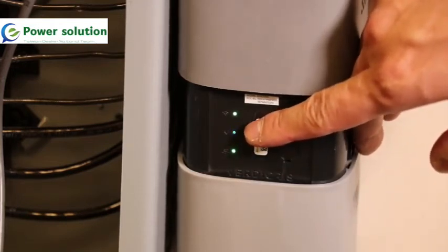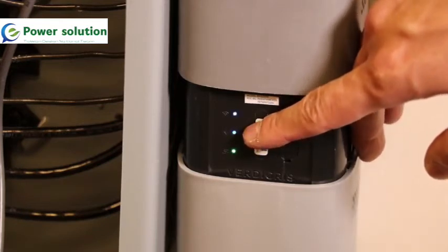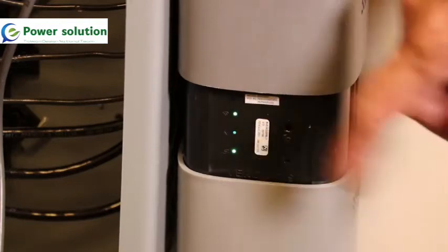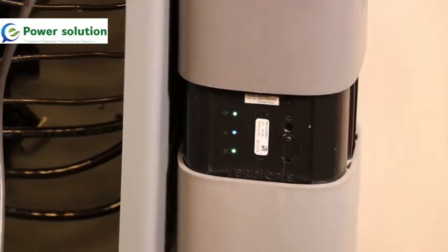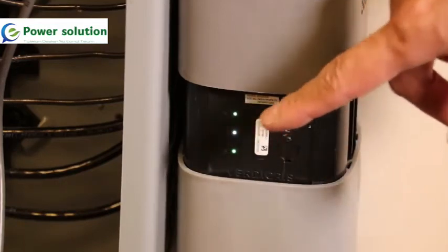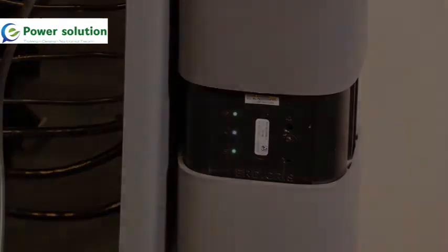The next light we expect to turn on is the voltage light, and the voltage light will go solid based on the color of the indicated voltage. We won't worry about the top light yet because that's related to the commissioning, and that's going to happen at a later process. So once we have a solid light on voltage, the physical installation for the panel is complete.